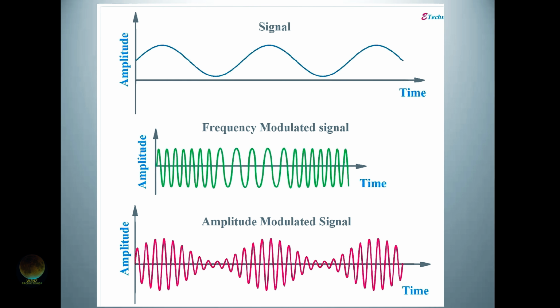Now if I talk and I'm on AM, the power goes up and down. So amplitude modulation, as the envelope goes up and down, that means the power output of the signal is changing. Obviously, if you've operated single sideband, you know that. If you talk louder, you get more power. That's why we talk loud, to get DX. The same with the digital mode, except it's analog sound from a sound card rather than human voice. So the important thing, I'm going to come back to this, FM constant amplitude. That has some implications down the line.